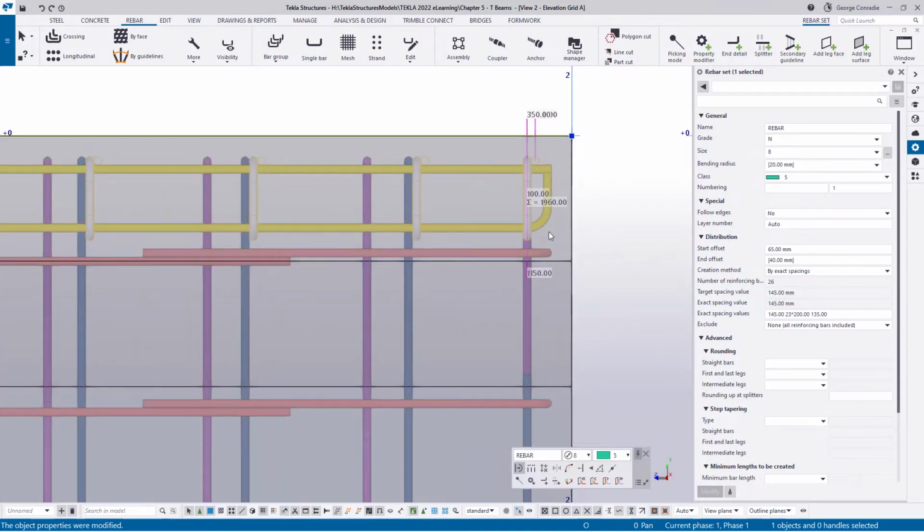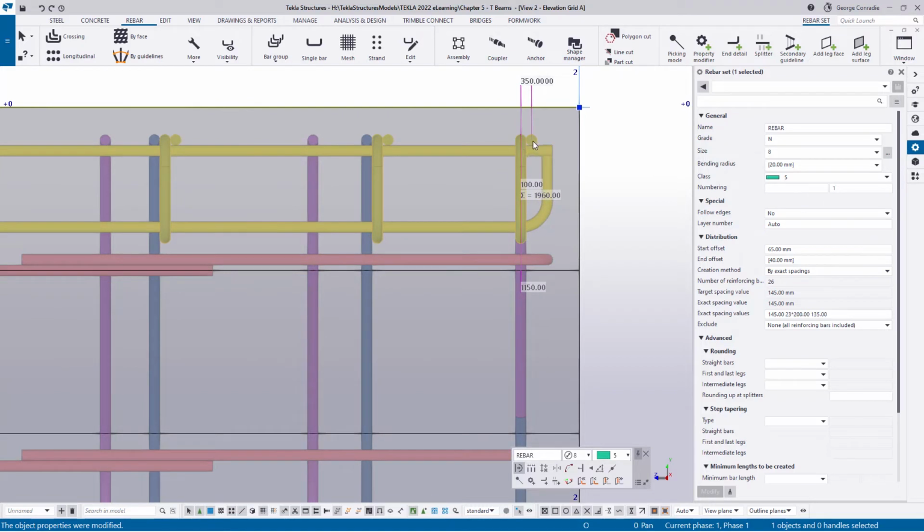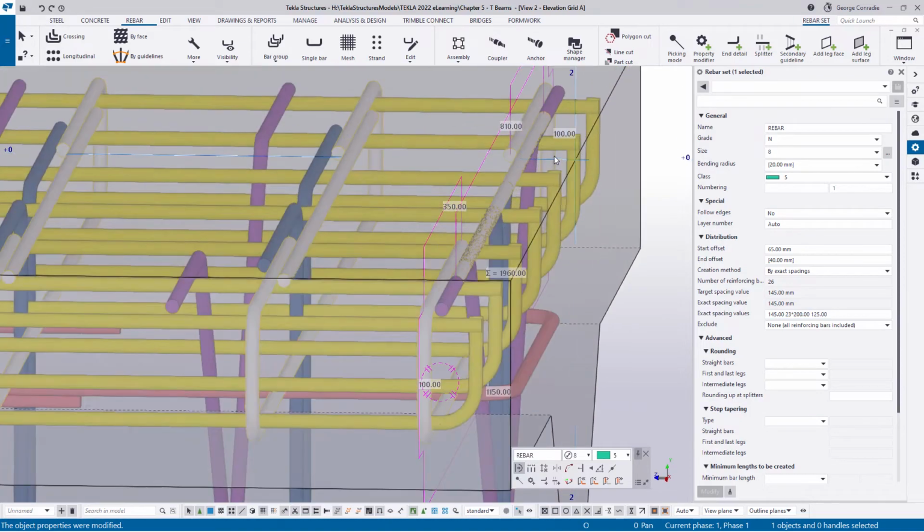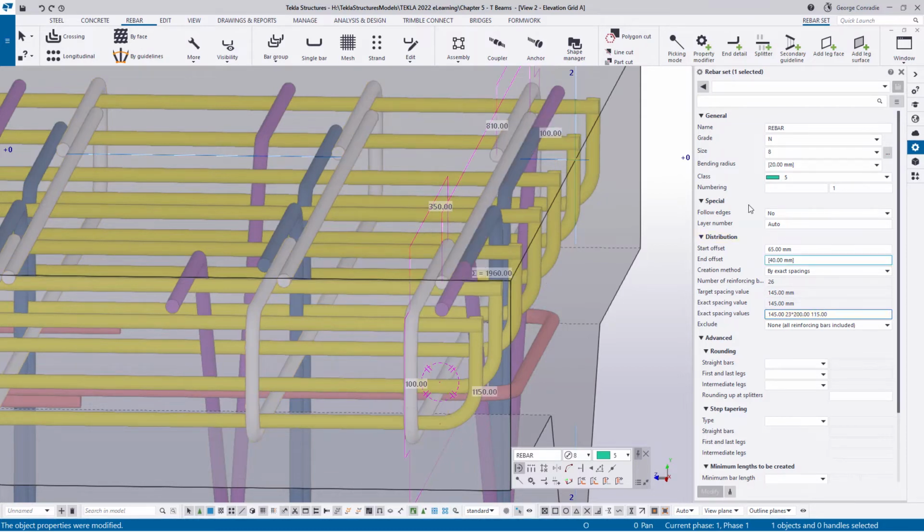at the end of that, I've made a calculation error there. They are actually doubles, so you've got to take twice the amount off. So that should be 25. And if I do that, you can see that works out nicely for us. Does it? No, it doesn't. You can see they're still lapping there. So we need to take another 10 off. So that will then become 15. If I do that, that now lines up nicely with this bar.